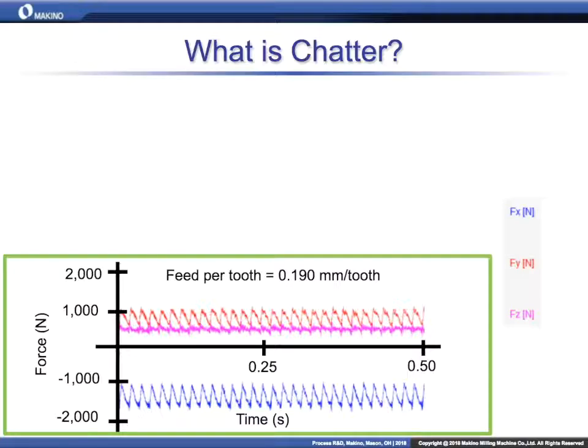In this case, we can generally assume that the cutting forces come from the chip thickness, right? Oh, yes. And sure. So we definitely assume that as you create a thinner and thinner chip, the cutting forces would go down. You would think, yes. Yeah, but you had this situation where you ran the same test, and then you ran it at half a thou, so we're going to show that now.